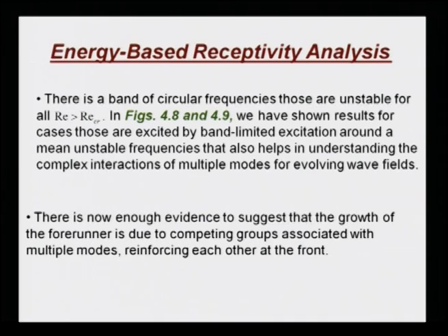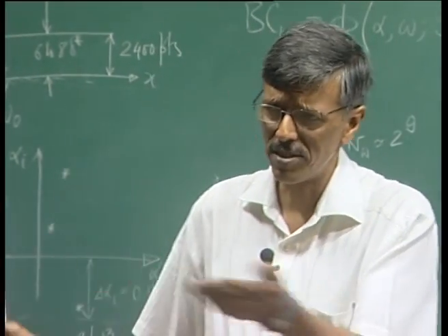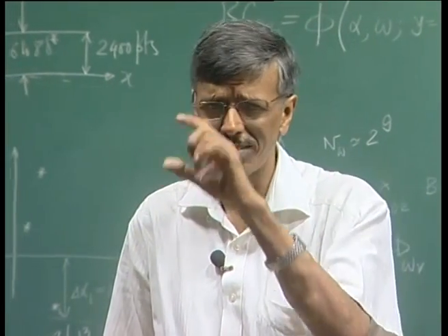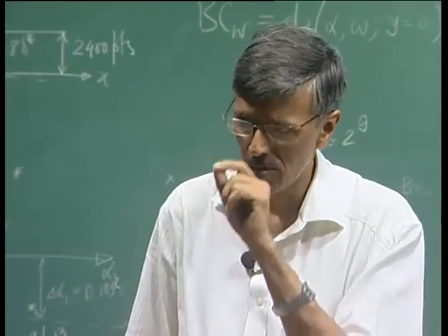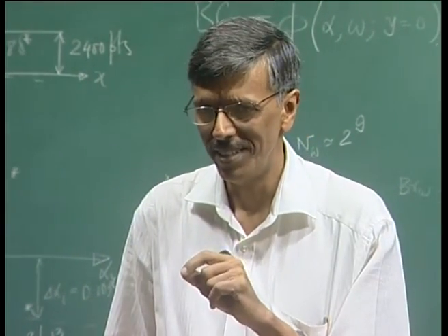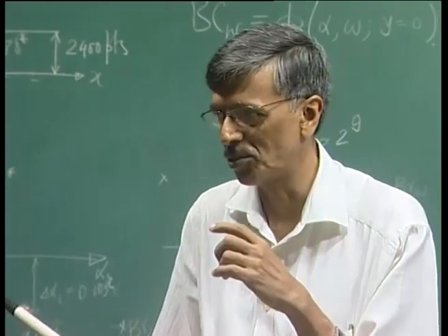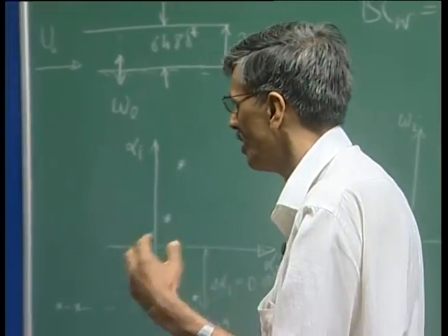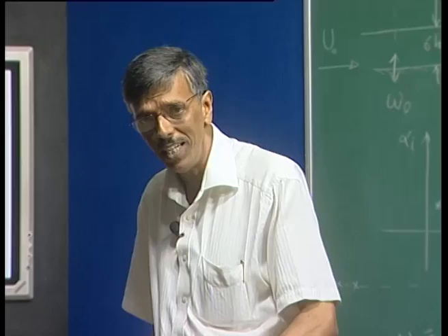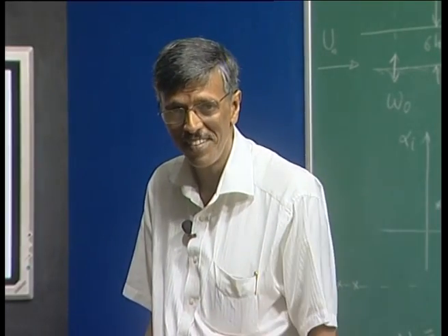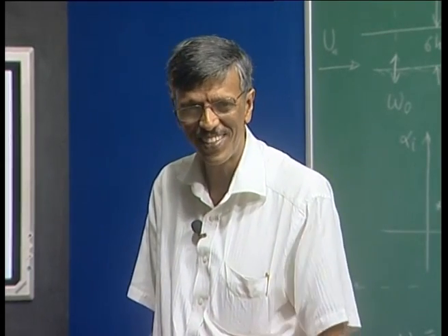However, we will talk about what happens when I look at the dynamics of a Blasius boundary layer itself, where I excite the system in a band of frequency where all the individual modes are unstable. But if I excite the system with that band, what happens to it? That is what we are going to study. Even though all the individual modes are unstable, we will see that the overall dynamics may not show any growth at all.